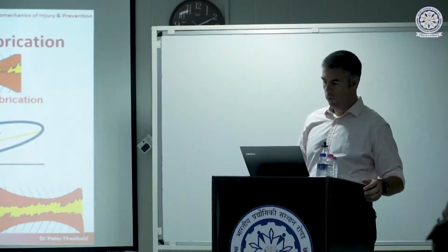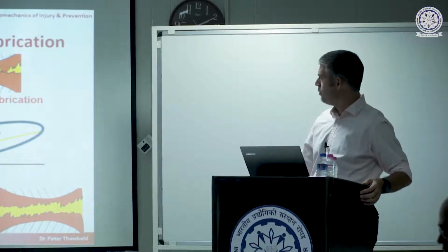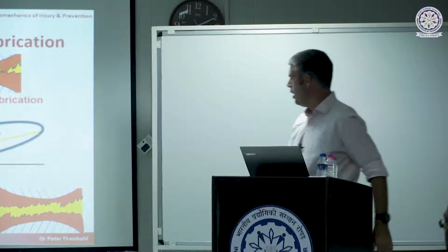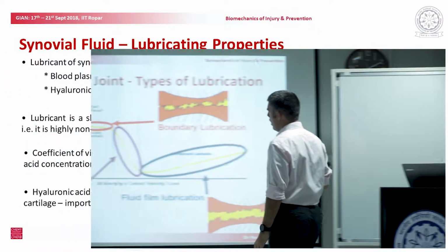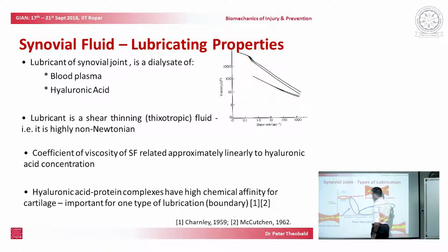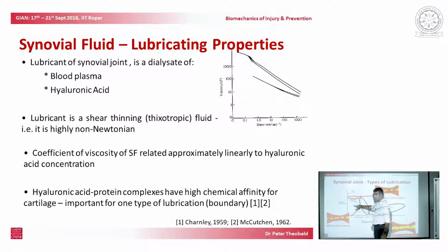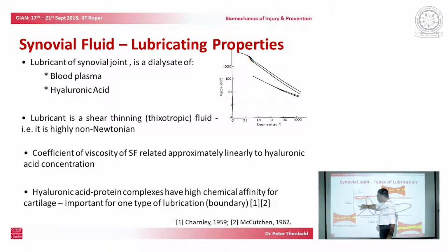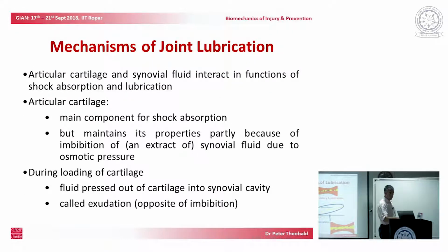Okay, so to finish off what we were talking about this morning, that's just a recap of the Stribeck curve, and the debate is how do we end up with a structure like articular cartilage that has such good properties, yet in reality fits about here on this plot of bearings when we consider its viscosity, velocity, and contact load.